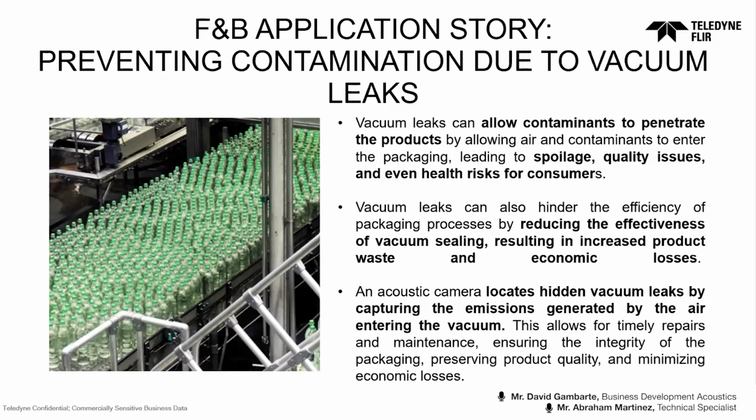Our cameras are a really easy, direct way of finding those leaks in the different production and quality processes. An acoustic camera locates hidden vacuum leaks by capturing the emissions generated by the air entering the vacuum. Naturally, it's a kind of counter use of the camera, but we already have a number of customers using the camera for vacuum leak detection, and it's a very powerful tool for it.